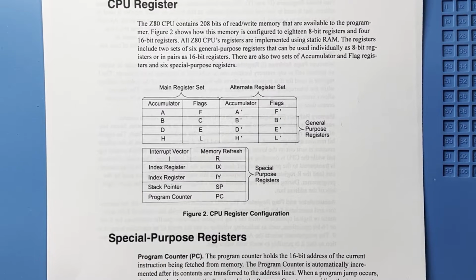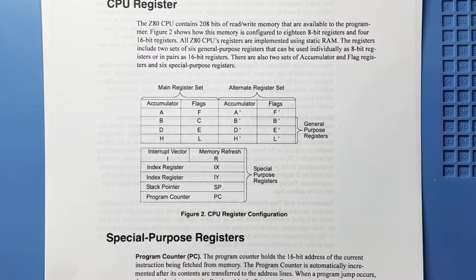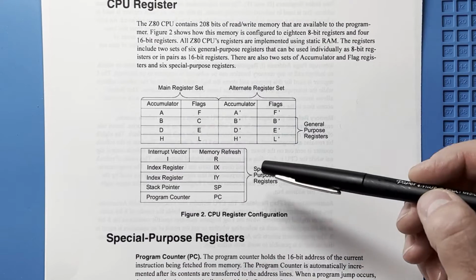For example, on a call command, the current address in the program counter is pushed to the stack. The call is made, and as long as the routine popped the same number of bytes it pushed, the return address will be the next 2 bytes on the stack. And when the return command is encountered, the CPU pops the address back into the program counter, increments it, making the command after the call the current command. We'll talk about this more later.